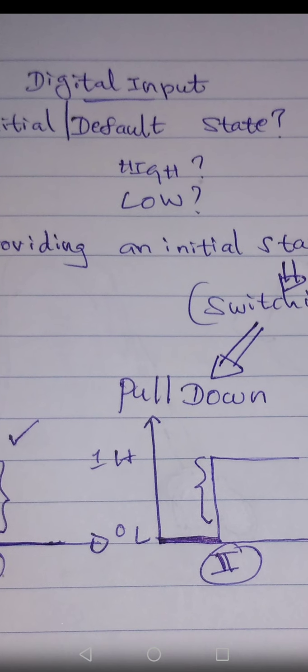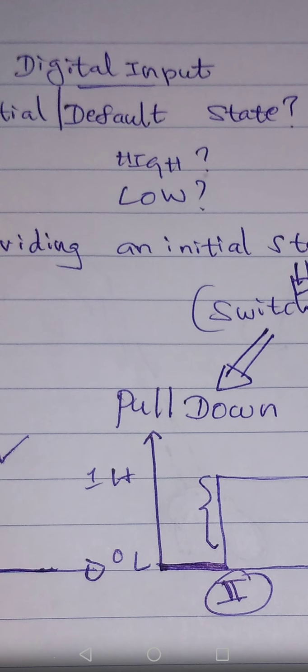If you say the pin state is high, then if I connect an LED and ground that LED to a ground pin, the LED should be on. You can try that out, it will not work. The LED will not be on. So now you may say it is in a low state because the LED is not on. Then I will connect the LED to 5 volts and take the negative terminal and put it in this particular pin, because it is low, according to you. Then also you will find that most probably the LED will not be on. You get what I am talking about, right?